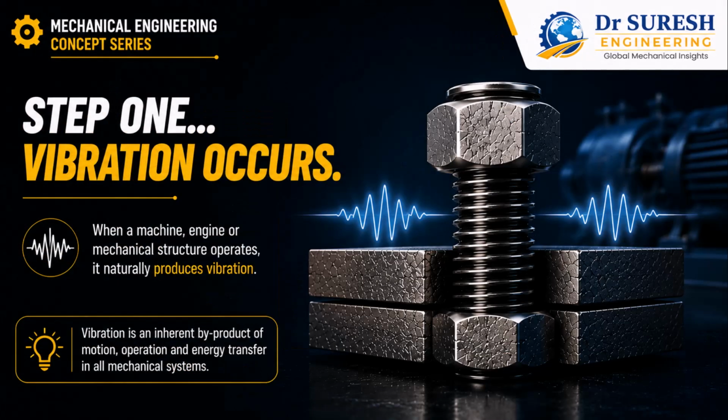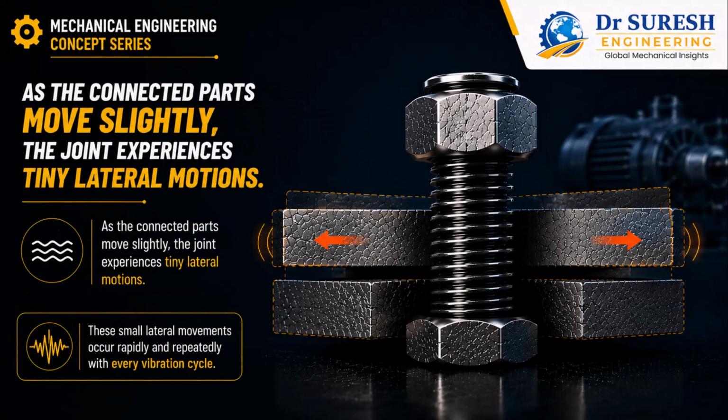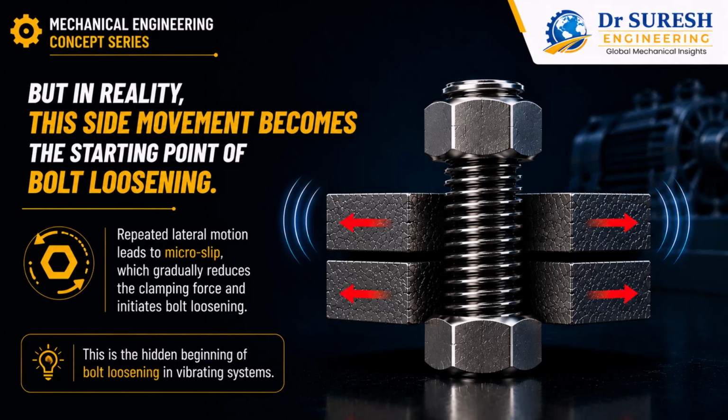Step 1. Vibration occurs. When a machine, engine, or mechanical structure operates, it naturally produces vibration. These vibrations generate repeated side forces inside the bolted joint. As the connected parts move slightly, the joint experiences tiny lateral motions. At first, these movements may seem insignificant, but in reality, this side movement becomes the starting point of bolt loosening.